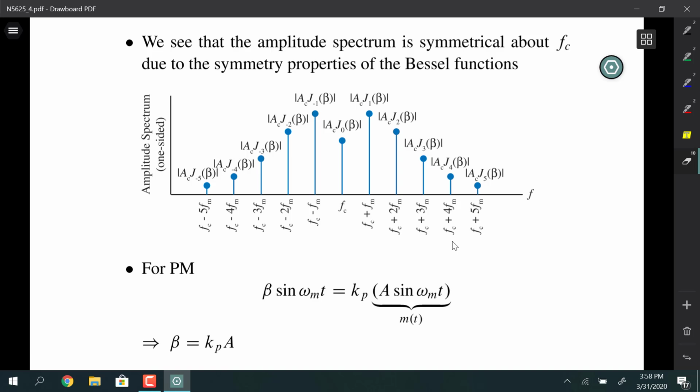What we're seeking is some measure of the bandwidth. And because we know the Bessel functions for beta greater than 0 are non-zero, we know that the spectrum actually expands over a very, very wide bandwidth that approaches infinity, but they're very tiny when you get to the edges.